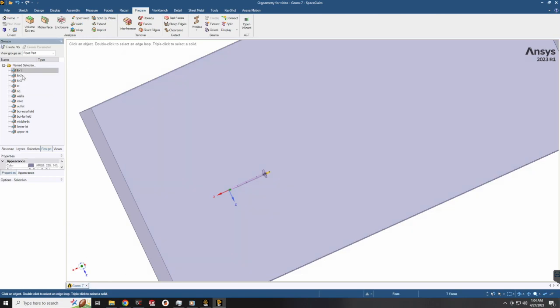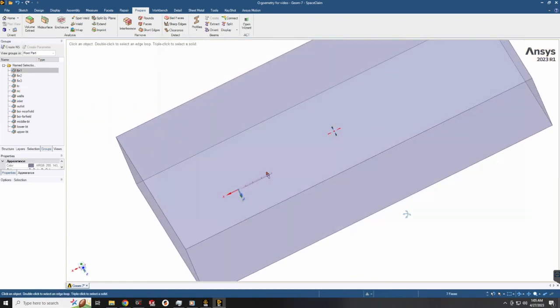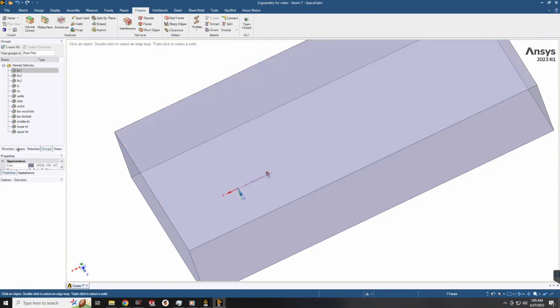Then all these other labels are for different parts of the rocket, because I wasn't sure if I was going to want to be able to define the surface mesh differently for the different parts of it. One thing I've noticed is that these named selections are not actually on the geometry I imported. They still exist if I deselect that. They're on the surfaces of the enclosure that interface with the surfaces of the original CAD model, because essentially the rocket doesn't really exist for the simulation. It's a void. There's nothing there. What matters is the enclosure, because that's where the air is.